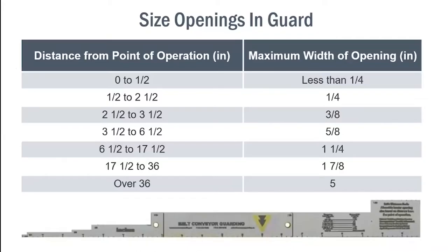For the through portion of that, we want to consider the size of the opening or gap in a guard relative to the distance to the hazard. This comes originally from table O10 in the mechanical press standard in OSHA, and is also in several of the ANSI standards, including B11, the robot standard, and the power transmission apparatus standard, B15.1, as well as their Canadian counterparts.